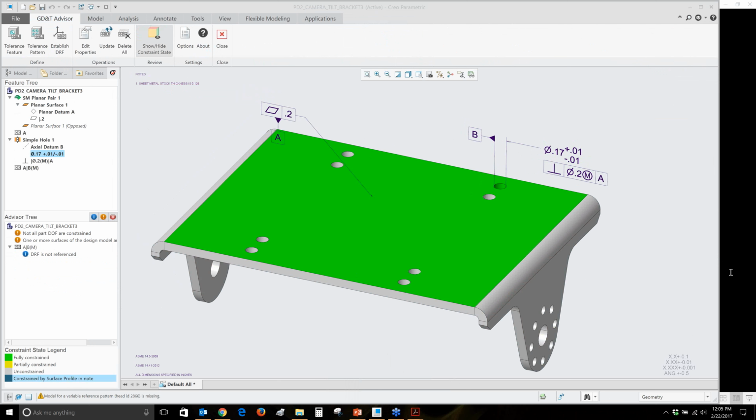If you're going to take this over to the next level, my recommendation is you're going to go to a detailed drawing with this. That view that you're going to be set up, you're obviously going to set it up for that view state that you're going to want to show that with. So you're going to want to associate those different dimensions, GTOL values or whatever they are, to those view states and set those accordingly inside of the drawings.